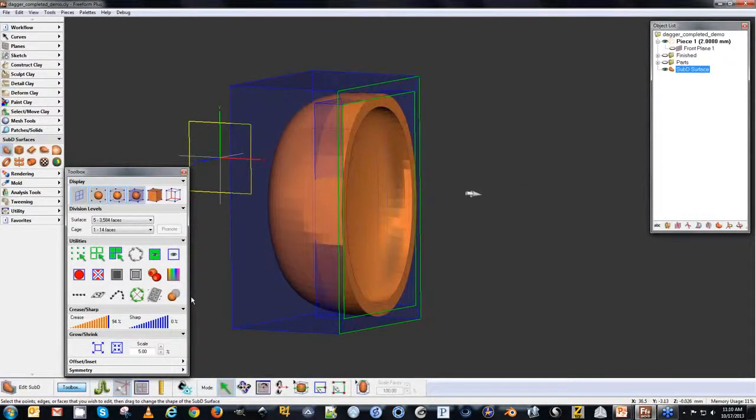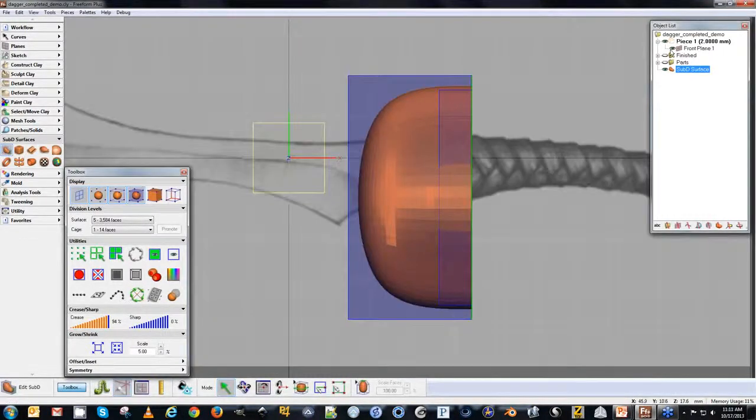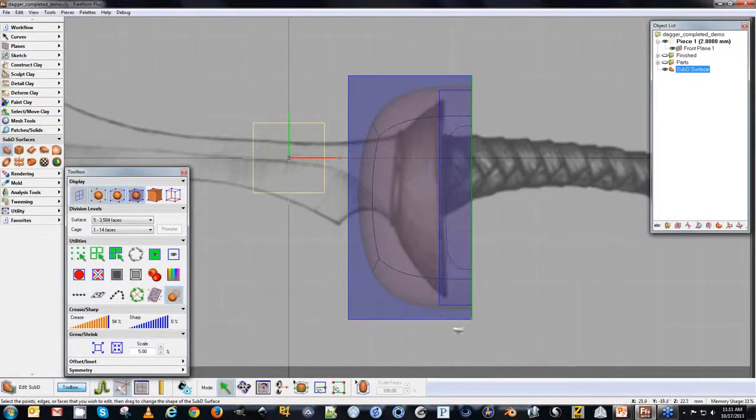So now I'm going to go back into my side view and turn back on the plane, go into see-through, and we can see that we're a bit off from the initial size that we were looking for. That's easy enough to fix. If I select some vertices, I start pushing and pulling. This is very common with polygon editing.